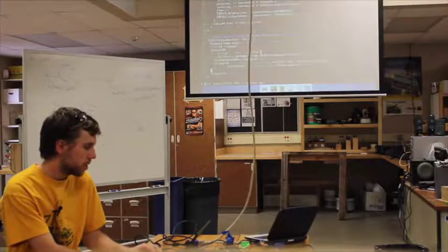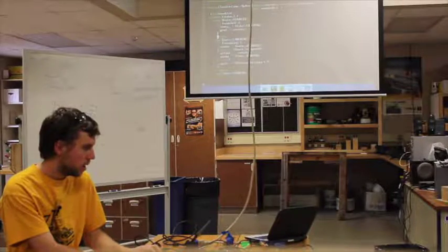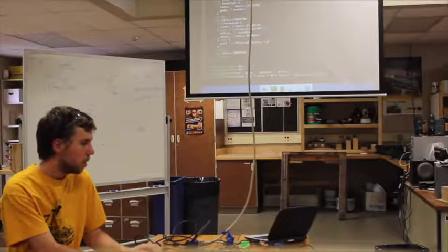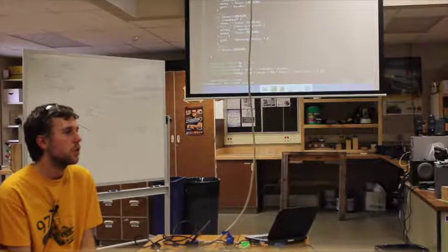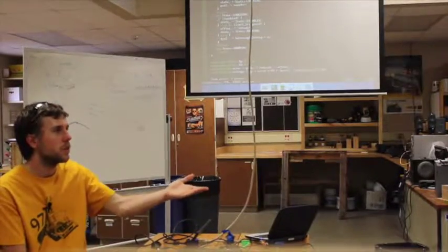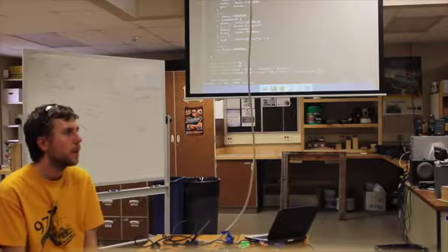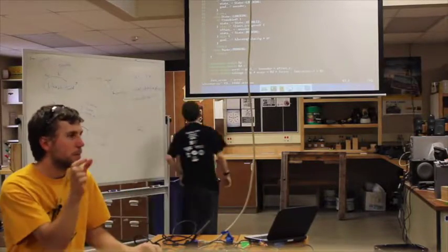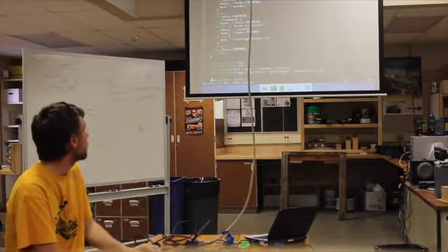So we have a little state machine in here. Does the state change? Do we care about its set line? Well, why not, right? If our control loop does not converge within, say, 5 seconds, that's also a bad thing. So we can just test that by saying, did the position go to where we expected it to, within some epsilon? But here's our state. So let's also check to see if we got the state running.